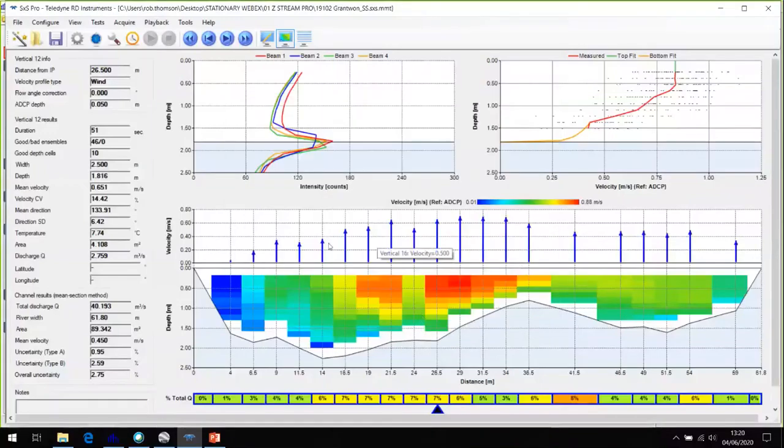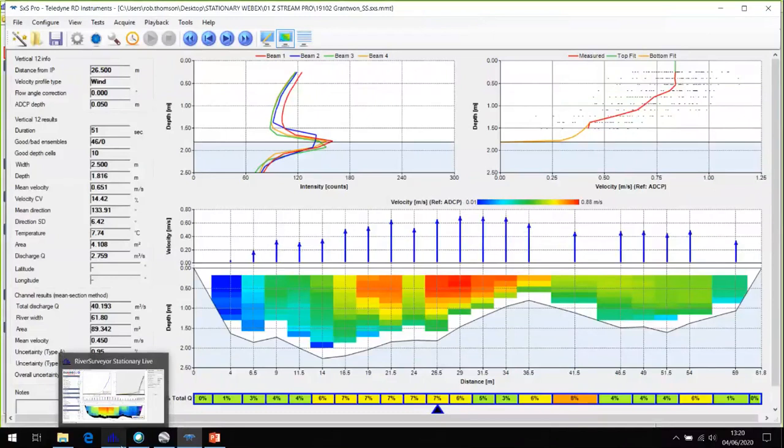Yeah. So it's important. If you're looking at the channel and you say everything's flowing directly downstream, or as good as you can see, and you see that the red line is skewed at an angle, it's probably an orientation or an azimuth issue. Okay, and so that's where you'd need to do your correction from. Unless sometimes you'll see these, and it truly is picking up something. Maybe there's a big rock on the bed, and it's actually skewing the flow out at an angle.